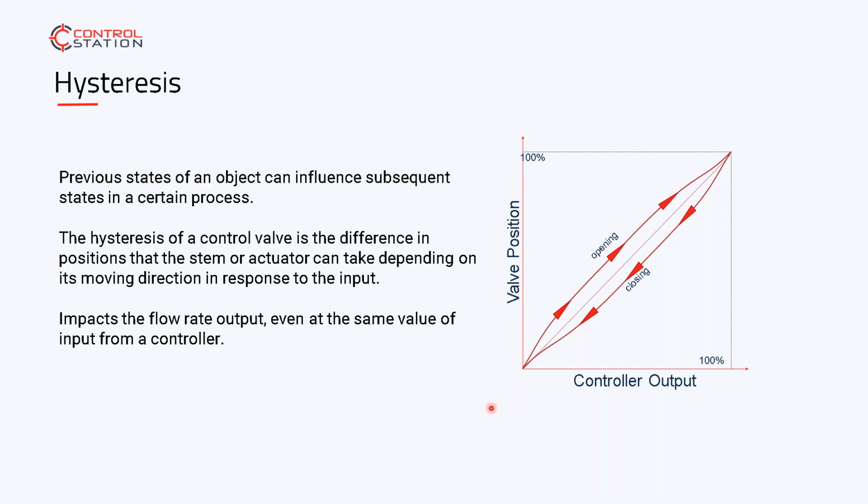Damien, if I could interject, yes. When we're dealing with loops and fail-safe modes, a lot of times there will be a spring return actuator to move a valve either fully open or fully closed. If the pneumatic actuator for the valve has not been designed properly, sometimes the spring action on the return can be greater than the force that you can apply with the actuator, so you end up with trouble there, and may end up with this pattern you're seeing.